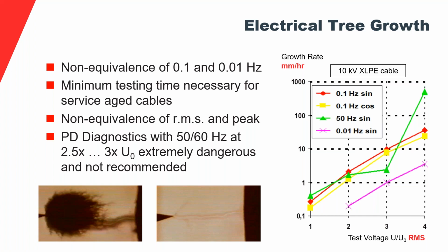And then very critical, if you do it at AC, with a power frequency method, and you go fairly high in the test voltage, you go into the exponential growth rate. Here you see in the green graph, and then you're actually damaging the cable pretty severely, even if you just do it a few minutes. And the common observation of our customers in the field is that they do this type of testing, and after that, their cables fail at a very increased rate.